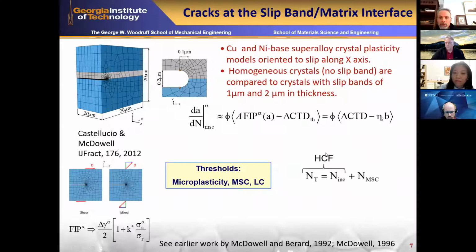And then, of course, we're all familiar with the delta K threshold concept in linear elastic fracture mechanics, which in general pertains to cracks that establish similitude with respect to the size of the cyclic plastic zone relative to the underlying microstructure. That takes about 5 to 10 grain sizes for the crack length in general. When the crack length is on the order of the microstructure, or just a few microstructure units, grain sizes, for example, we have the lack of that similitude. So we have to be careful, and we have to employ appropriate small crack growth relations.